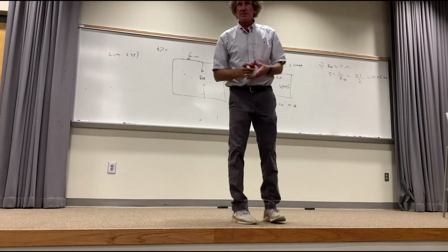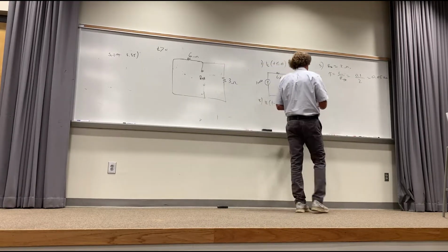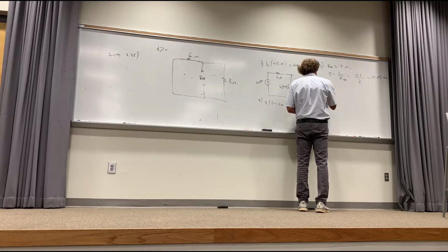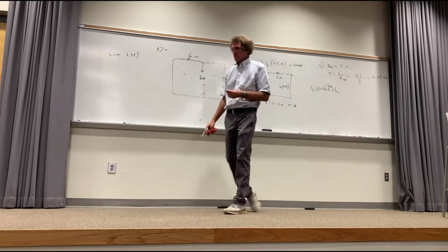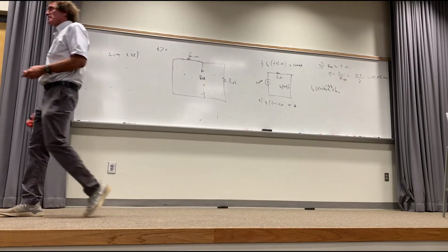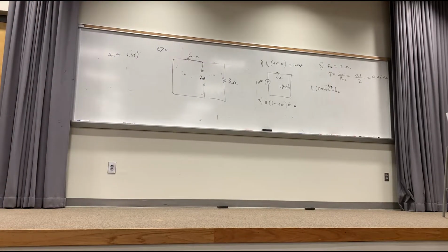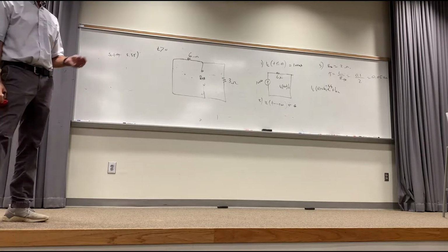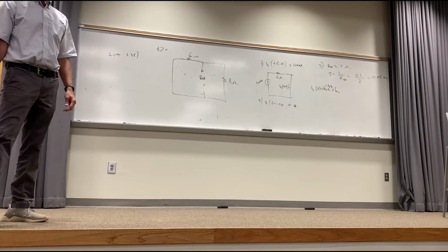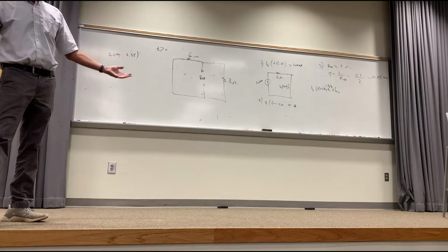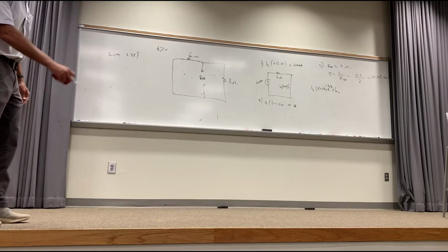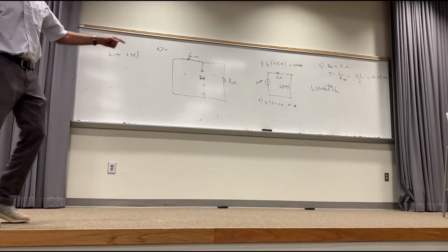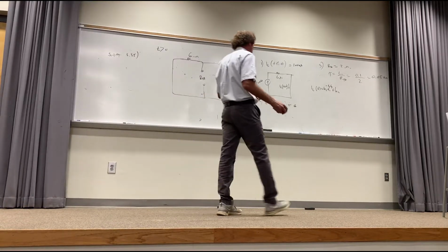Now we put the equation together. We say, I know my I L of t is equal to k1 e to the minus t over tau plus k2, correct? I'm just putting down the general form. Remember, the k's in this have to do with current. Now when you look there, what happens? Well, k2 is what? It's the value of current at infinity, isn't it? What's the value of current at infinity? I hope I put it there. 0. Is 0. So K2 luckily goes away.